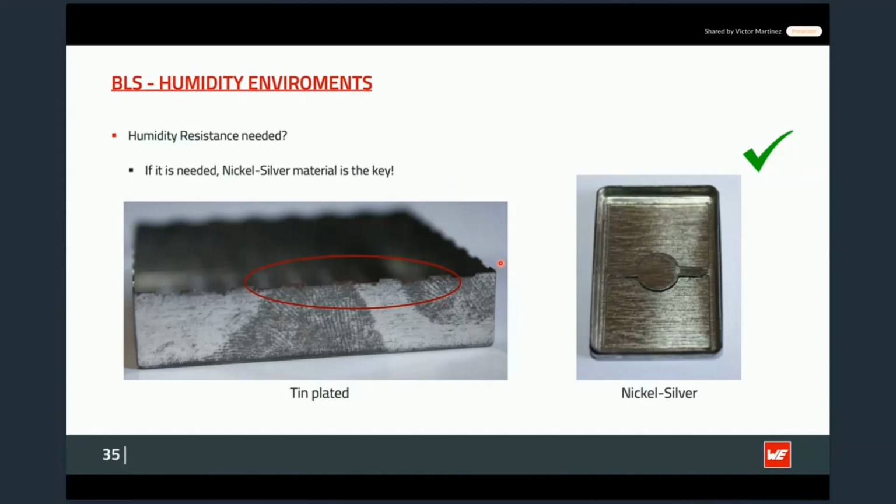This oxidation problem won't affect the shielding effectiveness. It will only provoke two side effects. The first is that it will be more difficult to solder it to the PCB. The second is that it won't look as good to the end customer. As we commented before, end customers want something colorful, stylish, polished, that looks good to the eye. If it is oxidated, they will probably think it is not as good as some other brand new product. But the main thing is that it won't affect the shielding performance of the cabinet.